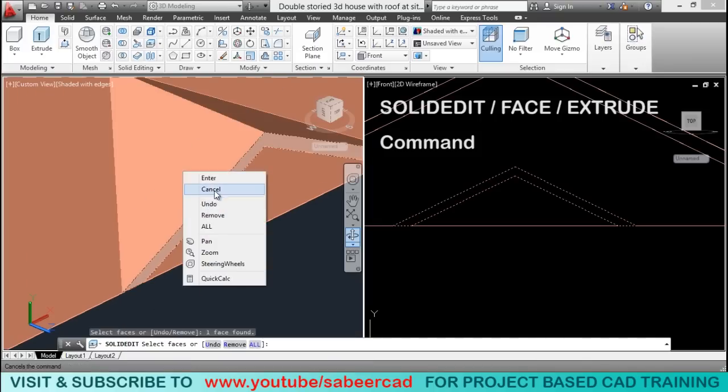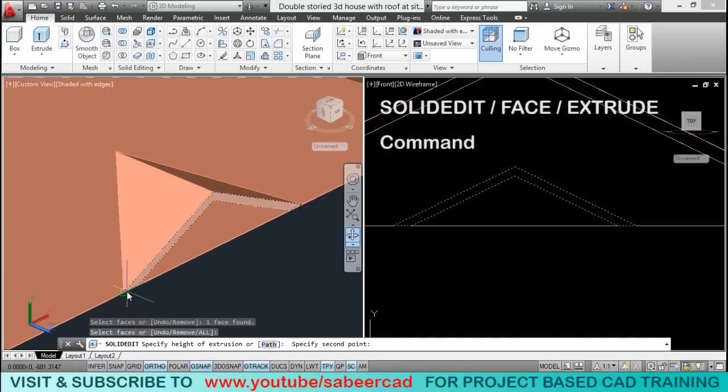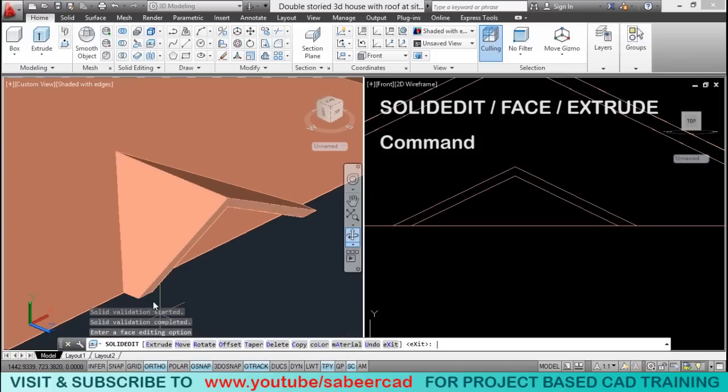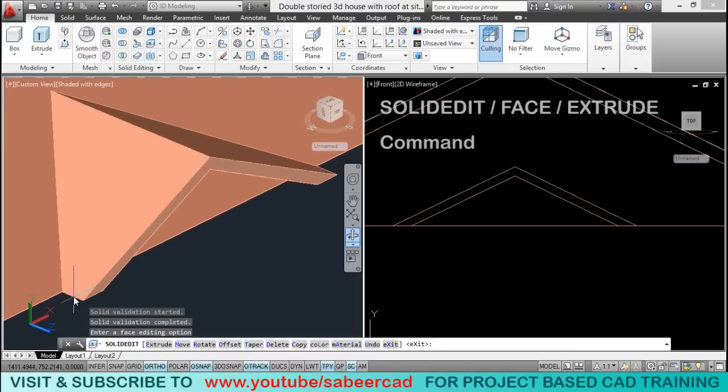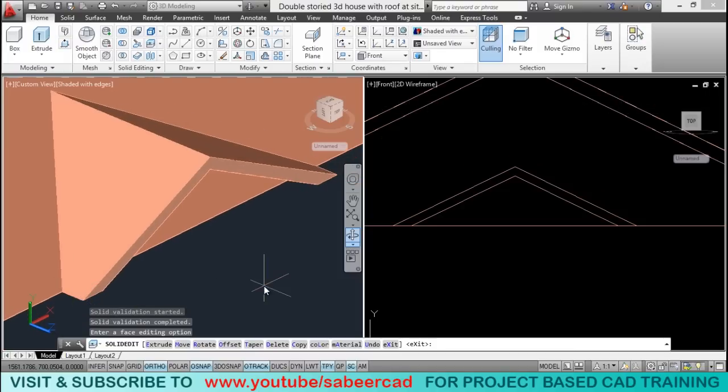So I'll just click on this face and just select the 3D solid. So that face is selected and I'll select this as the base point. When I'm asked to give the second point, I'll give 15 cm. So I'll type 15. Now it will ask you for the extrusion taper angle. I don't want to give any angle, so I'll just give an enter. Here, the height of extrusion is provided by specifying 2 points. Alternatively, you can also give a value for the height.